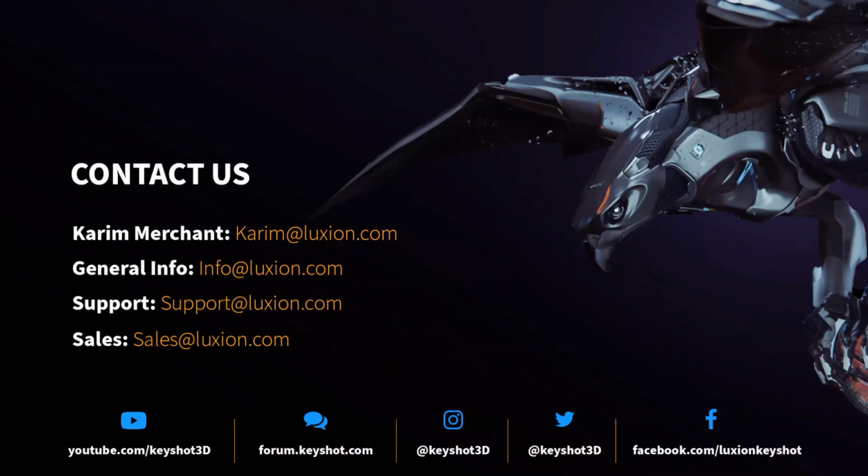Someone's asking about toon passes. I think someone's saying the line weight looks different in the final render than what they're seeing on their screen. Any settings or tips to help this? We did make some changes to the toon shader in 10. I don't know if you're seeing that on 9 or on 10, Joe Bloomfeld, but I would try and get the 10 version. You can get that free trial, that non-watermark free trial, if you don't already have it, and check that out. And if it's not matching the real-time versus the render view, that sounds like it could be a bug. So please file that with our support team.